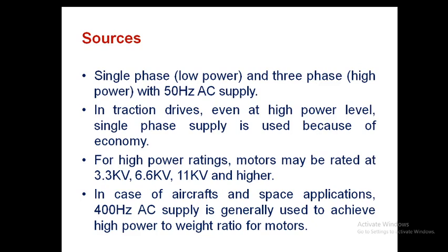That's why in aircraft and space applications, a 400 Hz AC supply is generally used to achieve a high power to weight ratio for motors. The motor is a major component, so to reduce the motor size in space applications, we increase the frequency so that the magnetic size will be reduced.